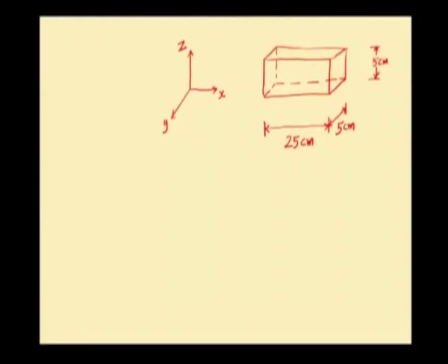Along the longitudinal axis, we have a tensile load of 300 kilonewton. So, tensile load 300 kilonewton is acting along the longitudinal axis, which will be the x axis. On the 2 other sides of this square bar, we have compressive force of 500 kilonewton. So, along z direction, a compressive force of 500 kilonewton is acting. Similarly, along y axis, a compressive force of 500 kilonewton is acting.